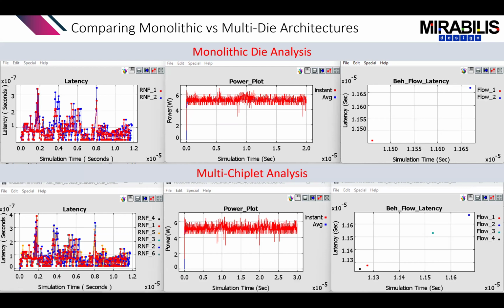But one of the nice things that you notice is the increment with multi-die for power is very small. It's not very significant. So that's a big advantage because each of the dies is going to have less power consumed than when you have a single die. So cooling also helps in this particular case. So you benefit from a thermal impact as well.